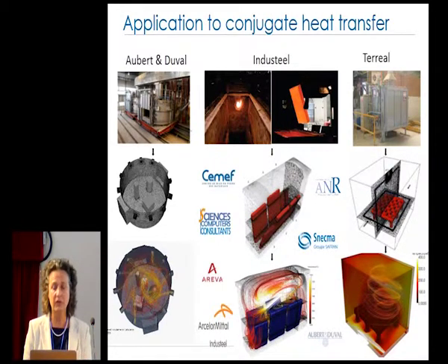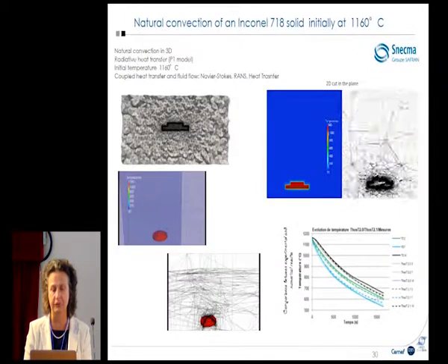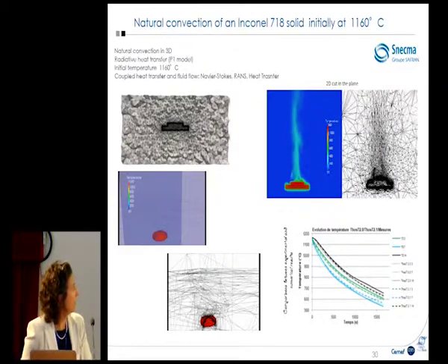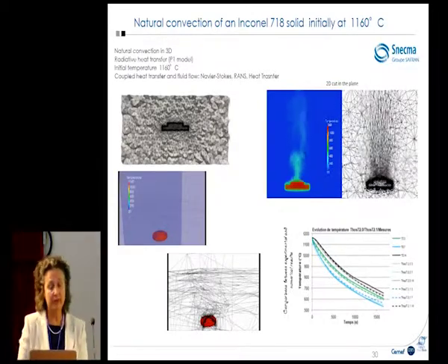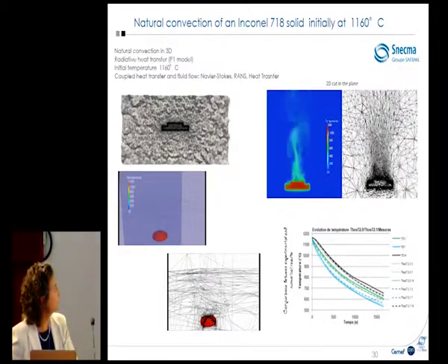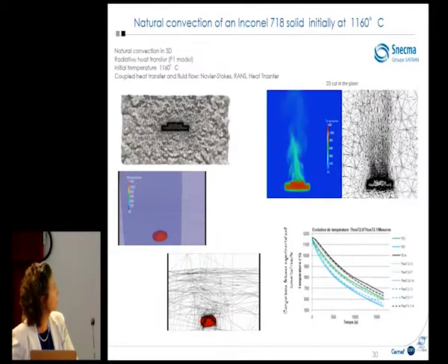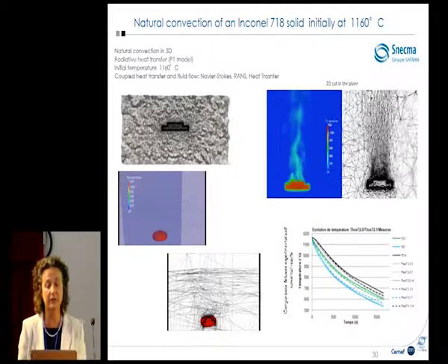And this nodule is very difficult to simulate, so we have to put a mesh on this in order to have the simulation of this nodule. So you can see here that during a tensile test we can have a debonding between the nodule and the matrix, and we create a localization of equivalent stress in this zone.